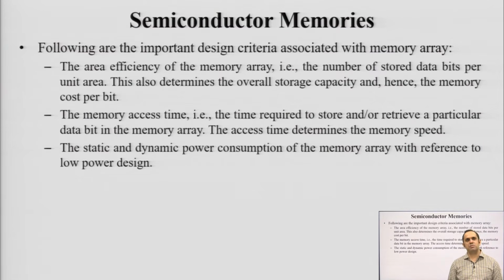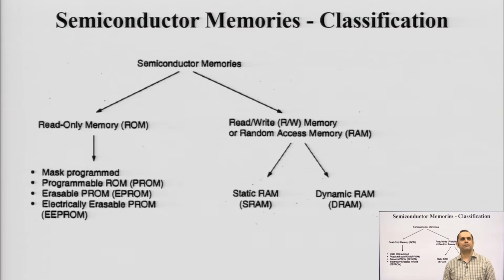The same applies to memory elements also. A dynamic memory element would have some kind of a capacitor across which you have stored your data, okay, or from that capacitor where the data was stored, you are fetching that data. Okay. That is a dynamic way of reading and writing, right. So, you have two basically variants, static and dynamic, and these are the major design criteria, or you can say performance parameters, which basically describe your memory elements, right.